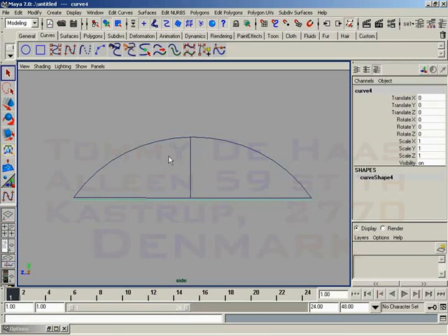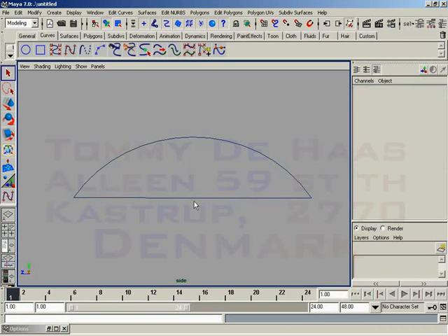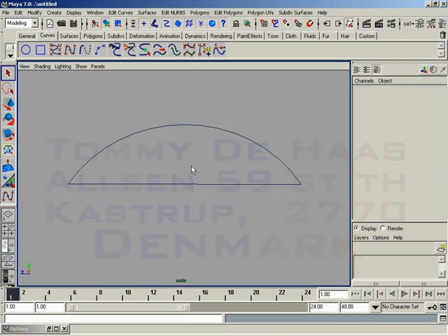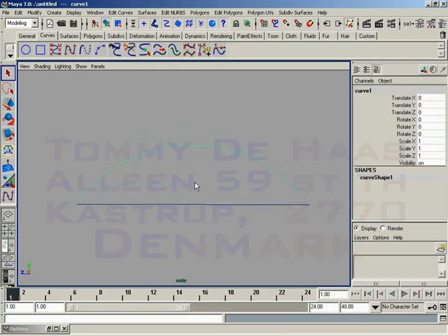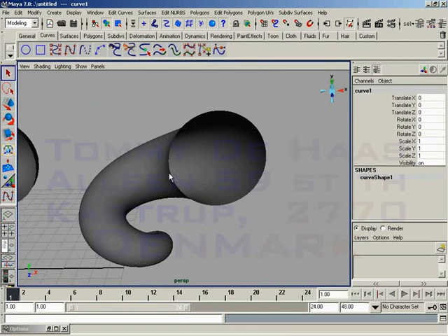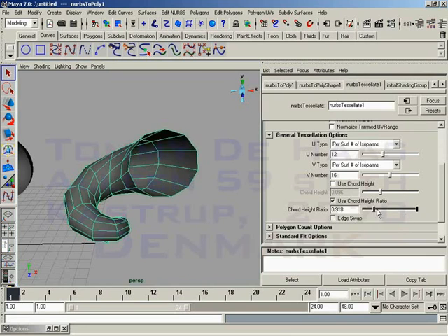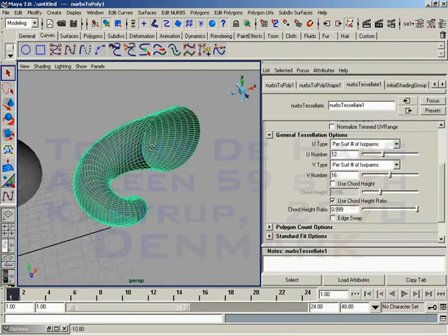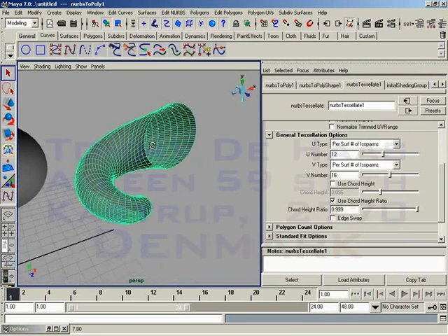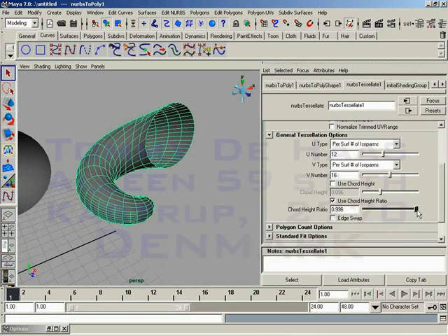Now, what's gone on in Maya 7 is they have actually reversed that. They've made it match what's going on inside the NURBS shape node, which is a whole lot more technical than I want to get into. They're taking what's going on under the surface and subtracting it from 1, so that inside your window, when you start playing with your tessellation, you have a slider that goes between 0 for low and 1 for high. So it's a little bit complicated, maybe made a little more so by the fact that they're inverting it now, but that's okay, not a problem.